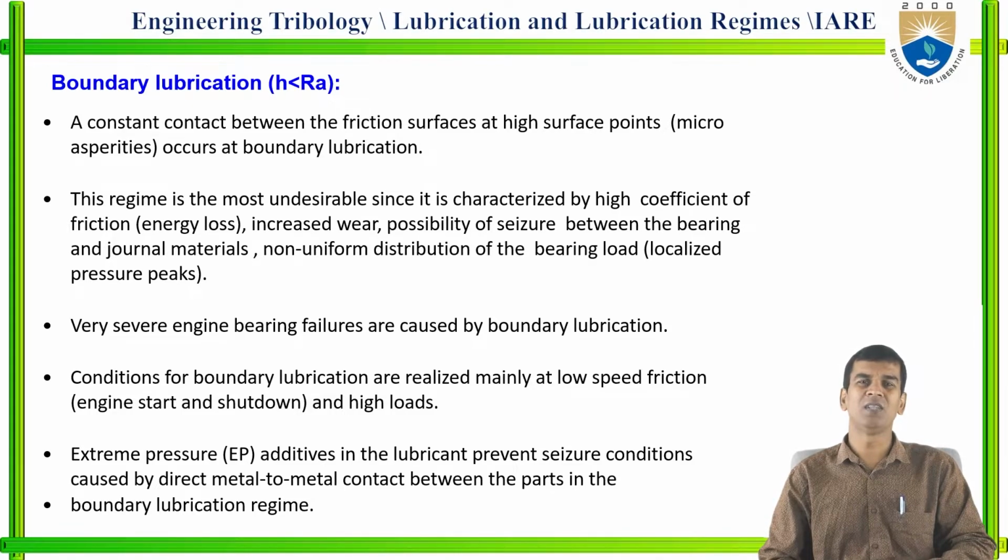Seizure is the locking of the surface tips between the surfaces. In addition, there will be non-uniform distribution of bearing load in boundary lubrication. Due to boundary lubrication, there are chances of severe engine bearing failures.